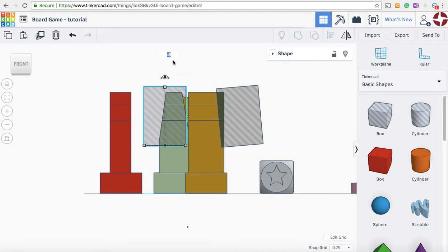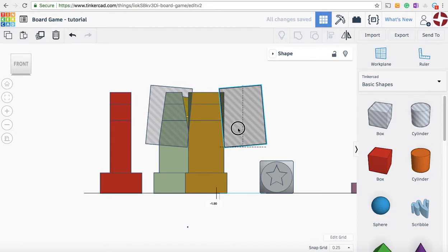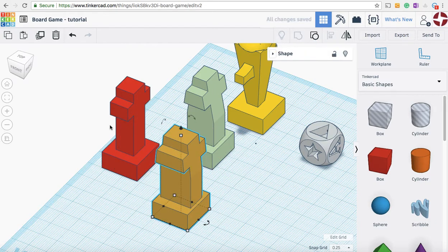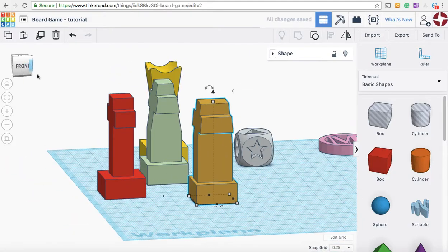What if I tried -10, sorry. There we go. And you can see I flipped it around to be on the other side. If I just move it in like that, and I can just get the other one right as well. Okay, this should be ready for grouping. So I'm just going to click that. I'm going to use my finger on the shift key to select the rest, and I'll hit group. So you can see I've tapered that edge there.